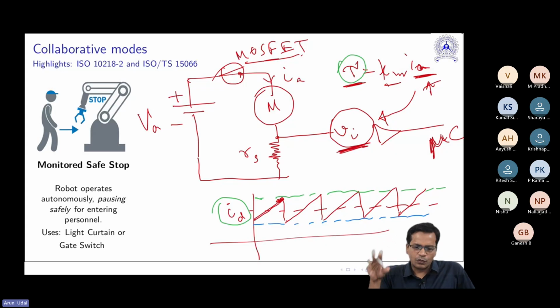Position you can control by taking feedback, making a PID loop that you have been doing since long time. Velocity you can control by duty cycle control, by PWM duty cycle on H bridge, Cytron motor driver or some kind of DC motor drivers you have used. You can do velocity control. You can do direction control also. Flip the H bridges, diagonally opposite ones, and you should be able to control the direction. You can control direction, position, velocity, and now you can control the current also. So you can do everything else.